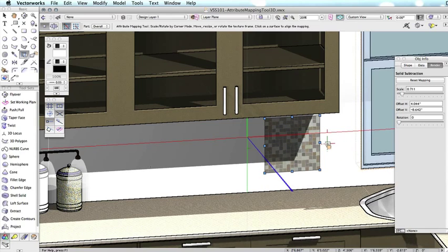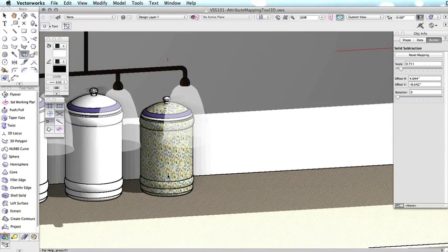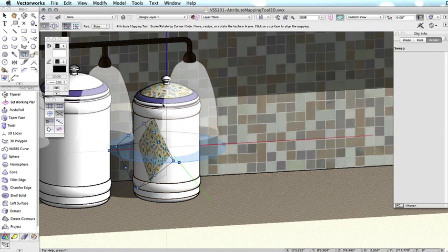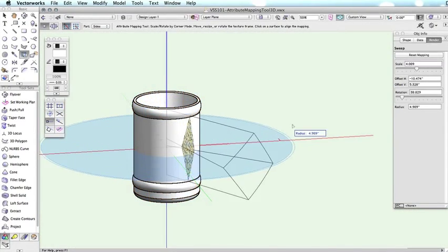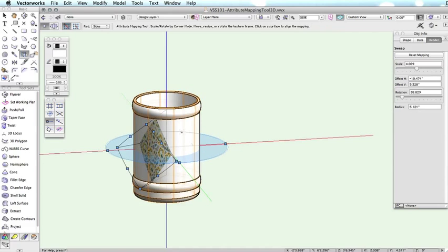If your map type is set to plane, you can also set the texture to a face by clicking on each face of the object. To continue mapping other parts of the object, select the next part from the part menu and repeat the mapping process. If your map type is set to sphere or cylinder, you will also be able to control the radius of the texture projection in 2D mode. Click on one of the 4 radius control handles around the edge of the circle and drag to the new radius. Click once to set the new radius.